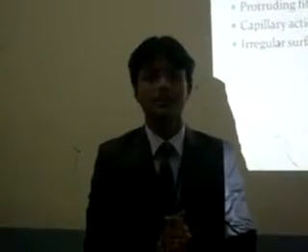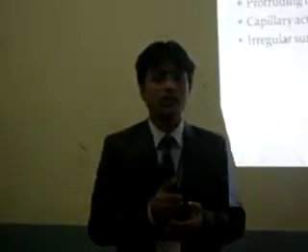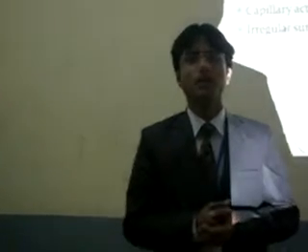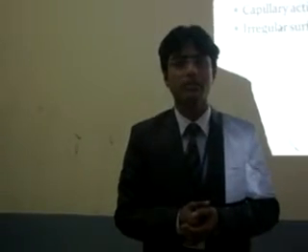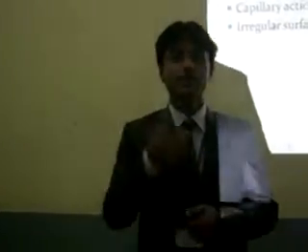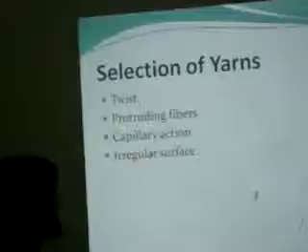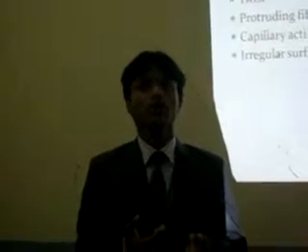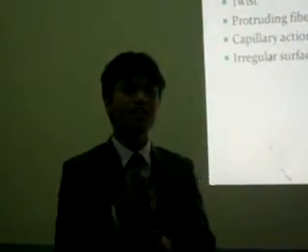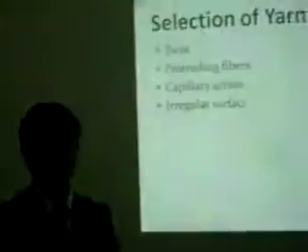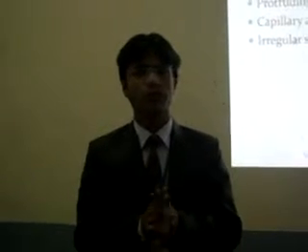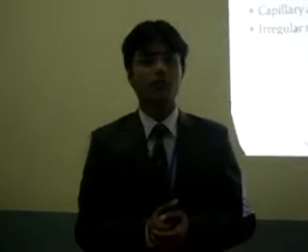Yarn produced from filament fibers usually contains less twist than yarn produced from staple fibers. The lower the twist, the bulkier the yarn, with increased voids between the fibers. These interstitial spaces allow for the trapping of particles that move through the fabric. In the case of staple yarn, however, twist also results in protruding fibers at the surface of the yarn. These small projections are ideal for trapping small particles. Additionally, they create an irregular surface which disrupts the formation of capillary forces as well, inhibiting the liquid movement.